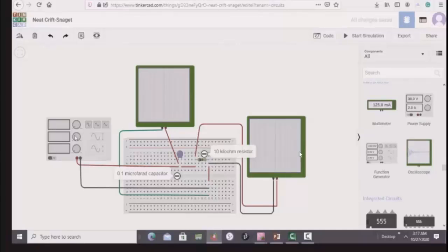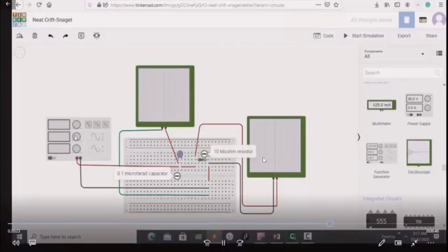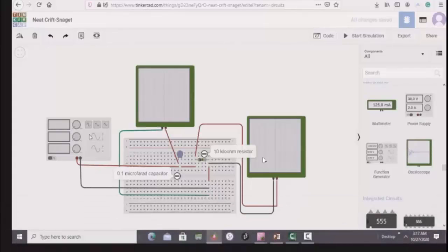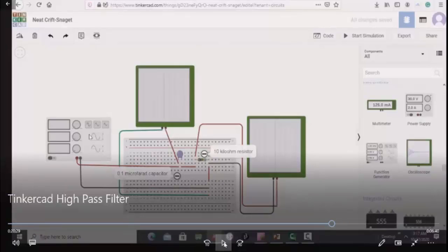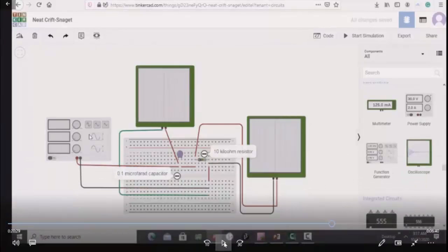Next thing that you want to do is you simply go on. So my cutoff frequency was 3000. So what I'm going to do is I'm going to take readings from cutoff frequency divided by 10 to cutoff frequency times 10, which means I'll take readings from 300 to 30,000 hertz, and I'll go in steps of 1000, and very close to my cutoff frequency.